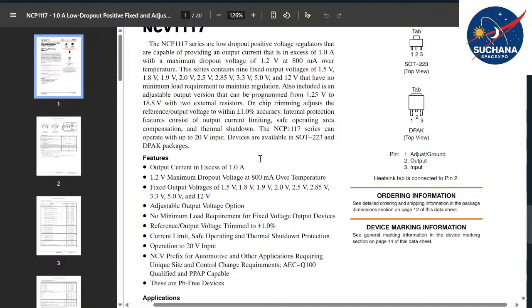So if you go through the parts of the Arduino Uno, if you go to the schematics of the Arduino Uno module, you can find those schematics online as well. If you search for Arduino Uno R3 schematics, you can find them there. In Arduino Uno, basically NCP 1117 5.0 is used, where the output voltage, VO or V out, is equal to 5.0.